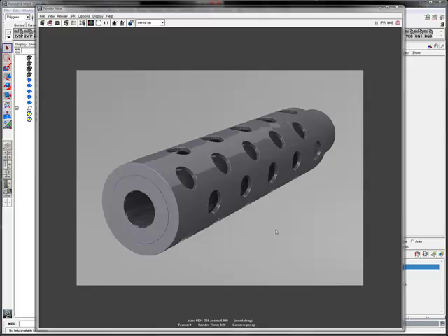The method that I see in a lot of the tutorials, however, starts out with a very dense cylinder for the object to be cut, and then very dense cylinders for the objects to cut the holes, and then they simply Boolean out the two objects and don't smooth it. They leave it as it is with this really highly dense mesh and all of these n-gons, and they can't smooth it because it wouldn't be able to hold its shape. And then trying to go in and fix the geometry afterwards to get it to be quads or triangles would be prohibitively difficult.